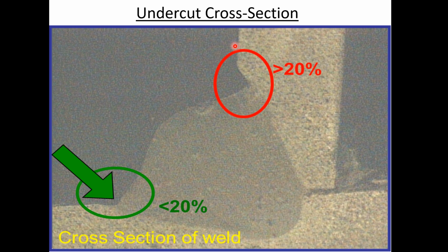I say this because in destructive testing, I've seen the smallest amount of undercut work its way right through the material in hardly any time whatsoever. It had an opportunity to start at the beginning, and then it just propagated through. Remember, I was talking about that heat affected zone that's a little softer, and it ran a crack all the way down right at the toe of the weld. So I'm always cautious about any form of undercut, even though it's not addressed in all specs, at the start or the last 25 millimeters.